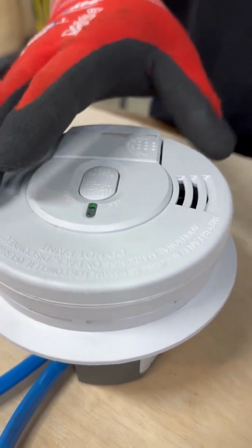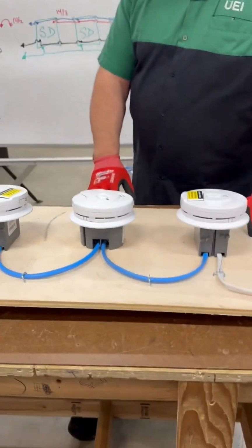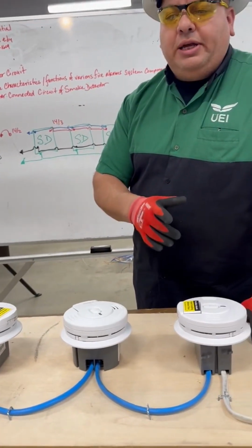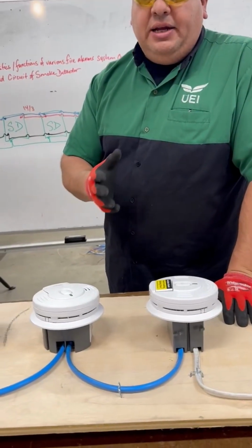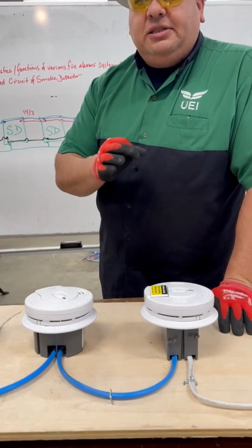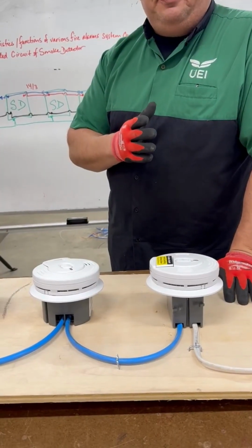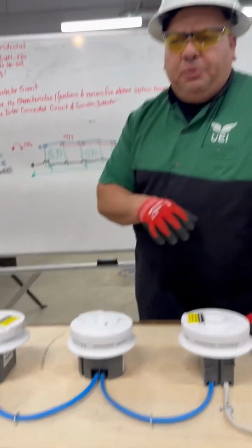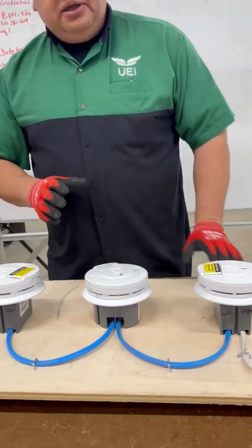One of the other things I bring to their attention is smoke detectors, some have photoelectric sensors, some have ionization sensors. Some authorities having jurisdiction will require that you have both. And we've got to explain to them what the difference is, the ionization versus the photoelectric, explaining the difference between the sensitivity levels. The Zoom and the PDFs do a great job of that, especially when we get into 160 and we start working with the commercial systems, it explains all that in detail as well. So keep that in mind.